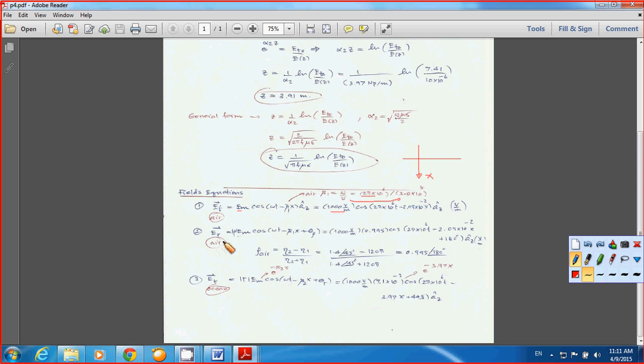Now the reflected electric field is equal to the magnitude of the reflection coefficient multiplied by EM, and since you have no phase of the reflection coefficient, because your sigma equal to 0, your reflection coefficient has only the real part. So actually theta of rho is equal to 0, and you have the magnitude of the reflection coefficient to be 0.995.